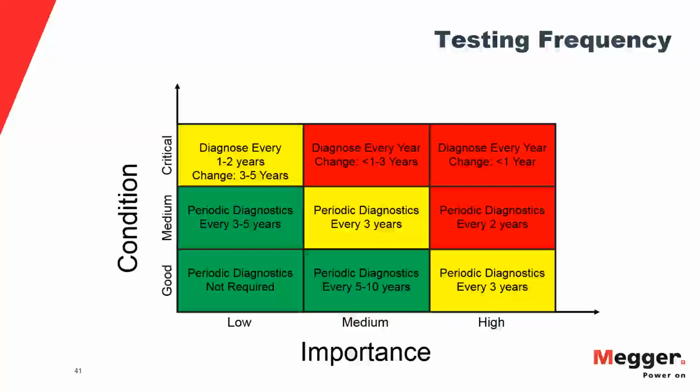But talking or something like that is not going to affect your readings. A radio that's passively listening, like an FM radio, is not going to affect anything. Just passively listening. A walkie-talkie certainly would. If you're using radios to talk to each other, that could affect your signals as well. Something like fluorescent light bulbs too, they can switch in that type of frequency as well. So high frequency radio interference type noises.